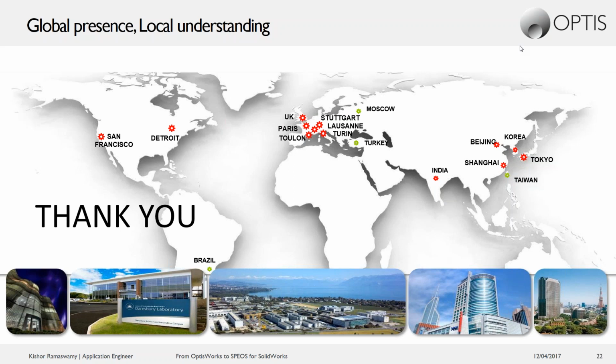The main difference for the SOLIDWORKS version has always been in the way that we are modeling the optical properties, and by treating the models as solid bodies instead of individual surfaces, the management of these bodies that are in contact with each other can now be handled automatically. The software is able to recognize the optical properties of individual bodies and also the external materials, and can correctly simulate this effect.